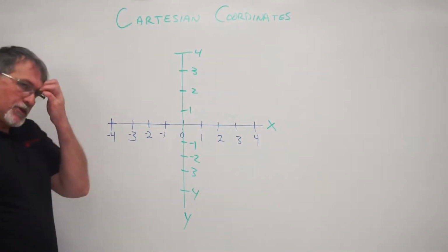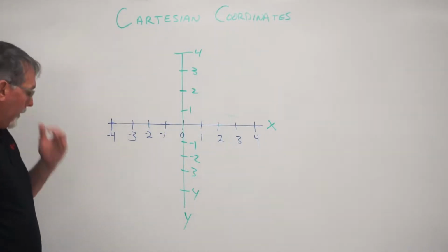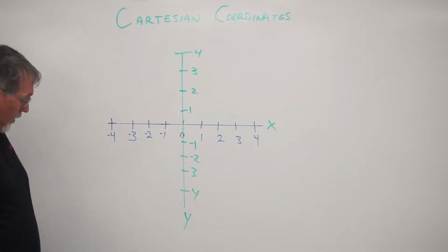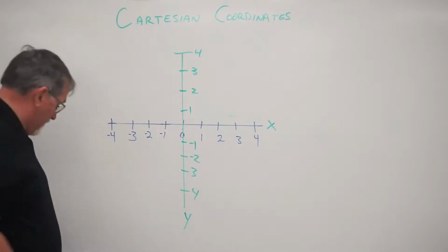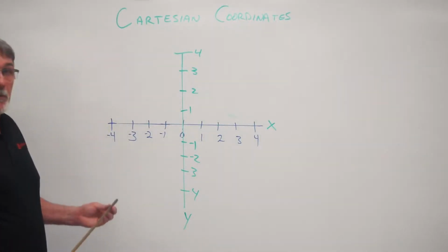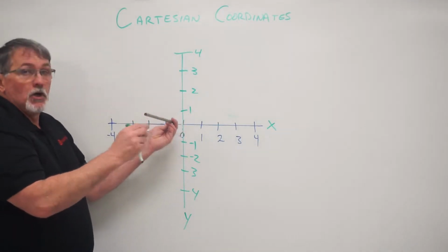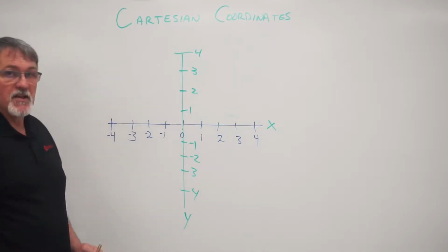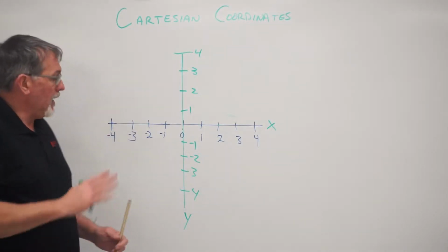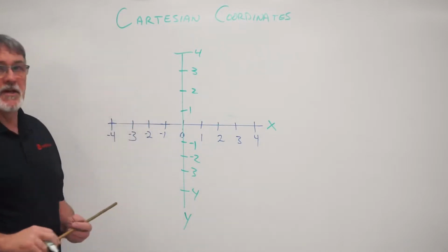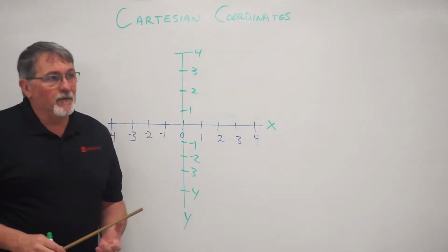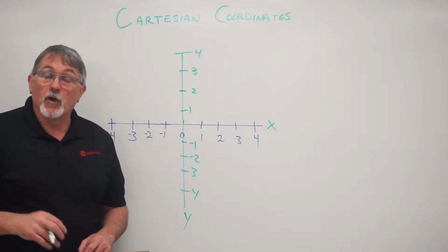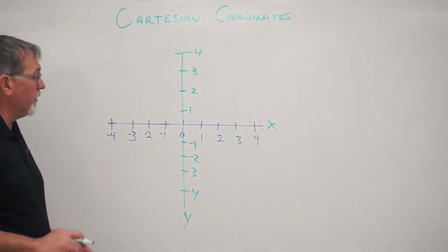We also often use a third axis in our milling machine, and that controls our tool position from home. That position is called the Z-axis. Now, it's going to be hard to see on camera, but the Z-axis is really this position going back and forth. So anything away from the part becomes a Z positive position, and anything into the part, below, becomes a Z negative position. And I say the part, it's depending on where you set your tool position, the tool offsets from, but it'll be a positive and a negative direction.